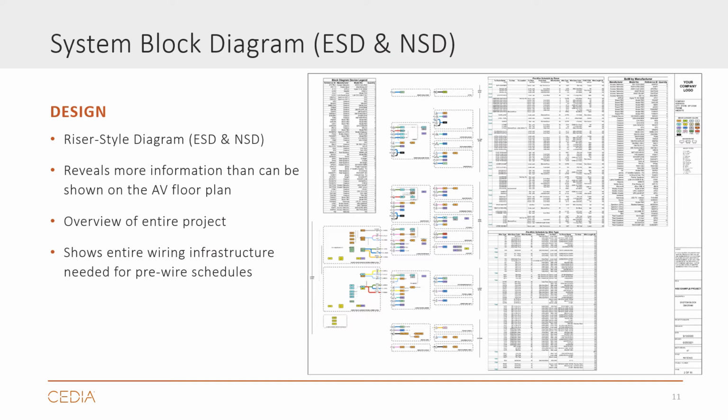So, the full system block diagram was developed to be sort of a template where you can lay out any project or brainstorm any conceptually new design. The layout generates the pre-wire schedules and bill of materials and becomes the foundation for all next stage engineering documentation, including schematics and rack drawings. And it was developed with helpful drawing guides for easy symbol alignment and layout.